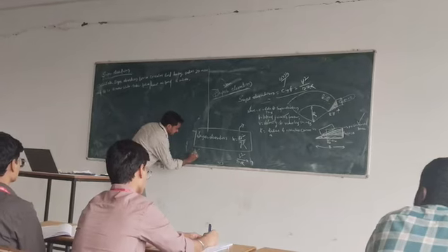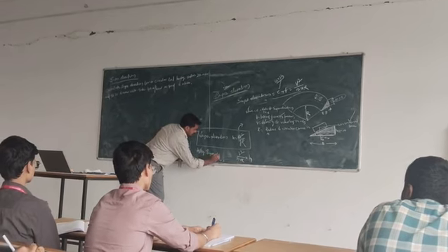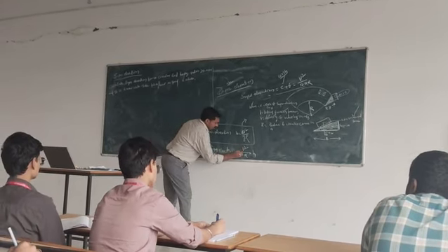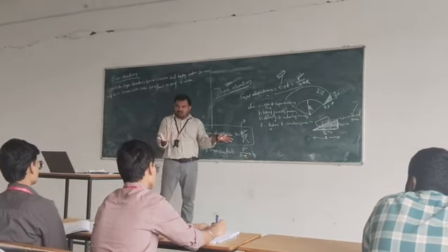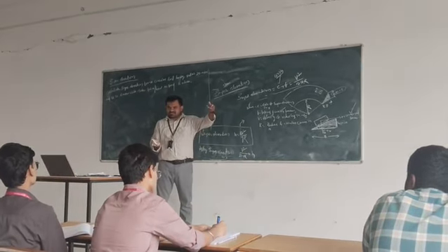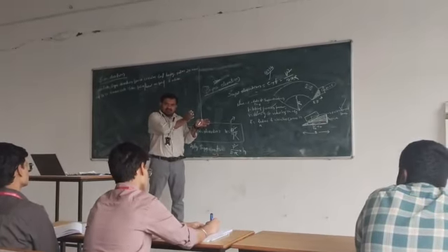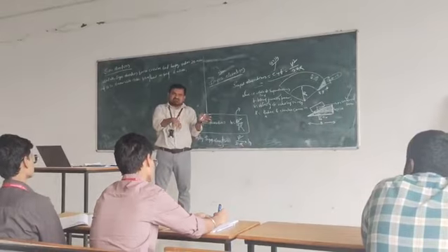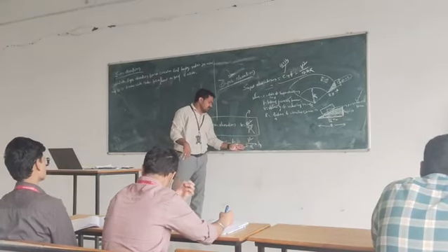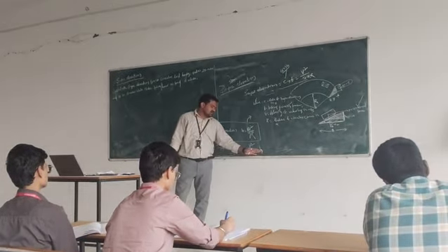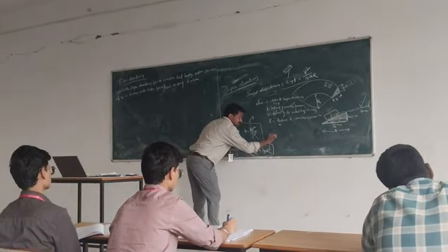Sometimes hilly areas will be there, so for hilly area superelevations, the formula is V squared by 225R. Hilly areas require more superelevation. Why? Because of the number of turning points and the number of overtaking points and cross sections that come. That's why more superelevation is required. So that's V squared by 225R, this much superelevation is required, E plus F.